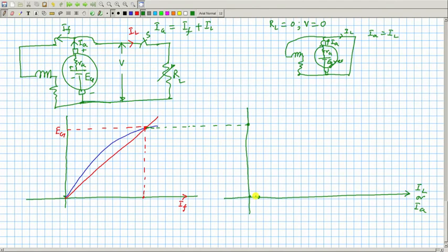So, one thing I am telling, the other extreme point in this particular case is so obvious that I can make it out. This final current will be this E residual, this much voltage, E residual divided by RA, this current, and there is no bifurcation of current here, it is shorted. This IA is IL, it will be like this.